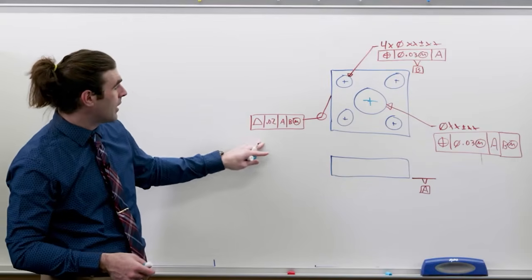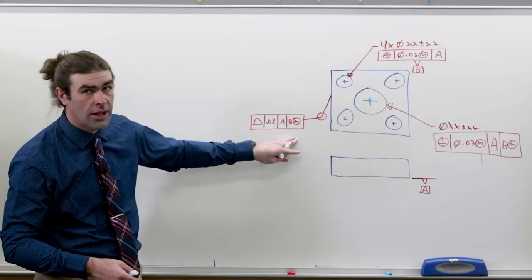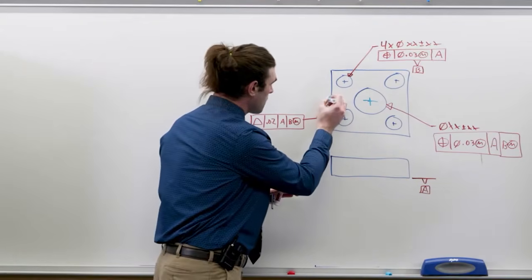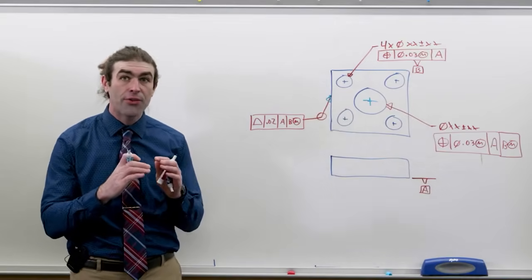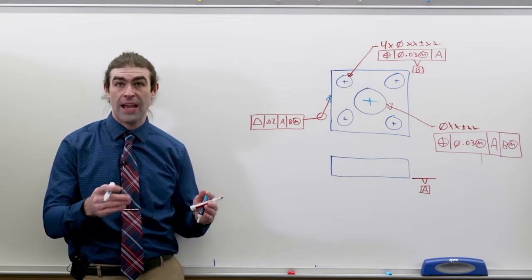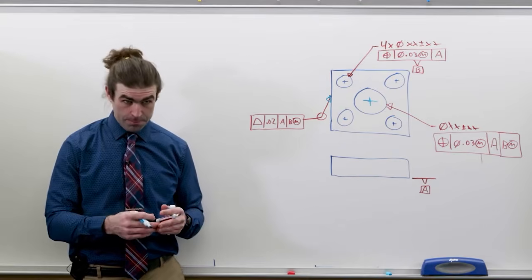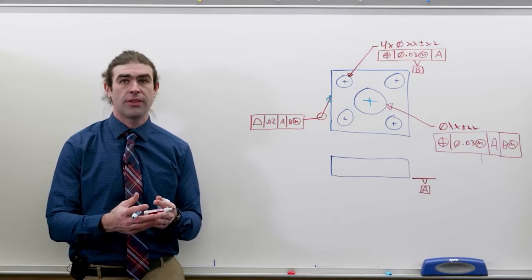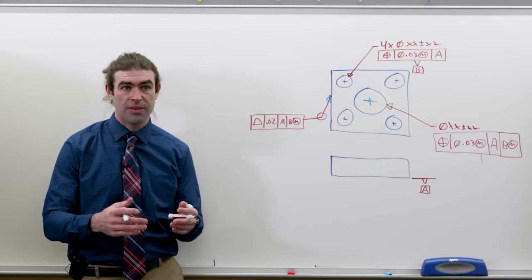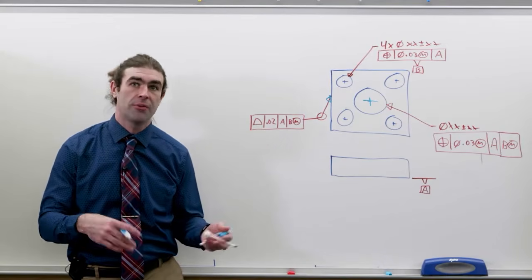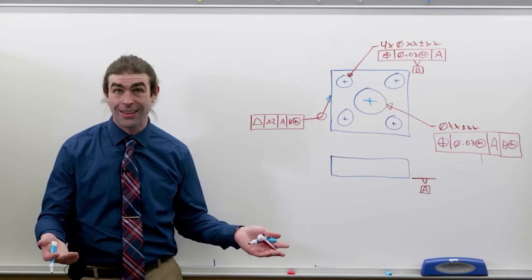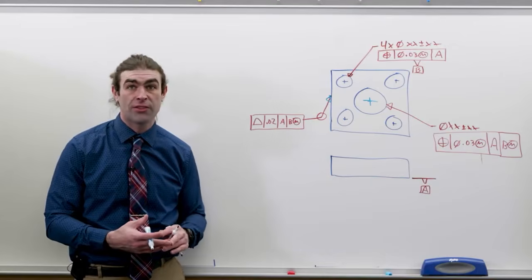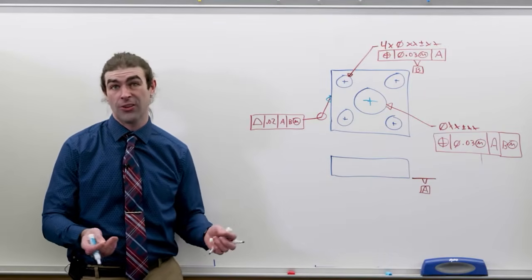So this outside right here has a profile to the same datums, A, B, and MMC. This is great if the outside of the part mates to air, which just means that there's nothing it's going to touch at assembly. So you could think of the outside of a television screen mates to air. A lot of things mate to air, and you want to be sure to give that kind of stuff as much tolerance as possible because it's not functionally very important.